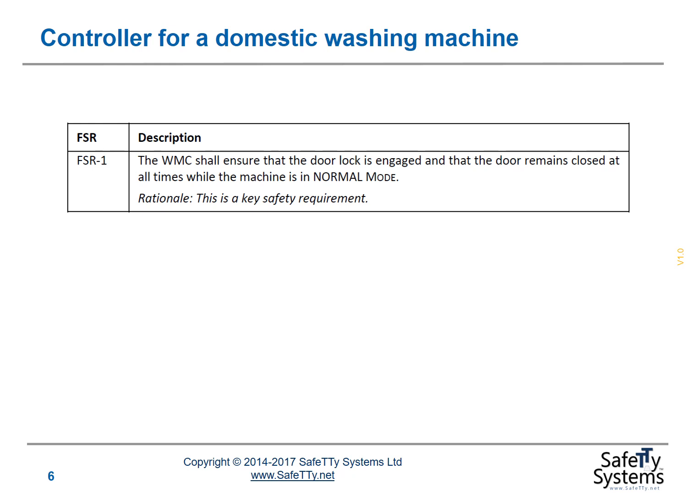So what we focus on in this video, and in much more detail in the book chapter, is the mechanisms that we can use to try and ensure that this is the case. We want to ensure that if somebody opens the door while the drum is spinning, we detect this and react accordingly. Before that, we want to make sure that the door lock is in place and the door is properly locked to avoid the risk that someone will be able to open the door in the first place.